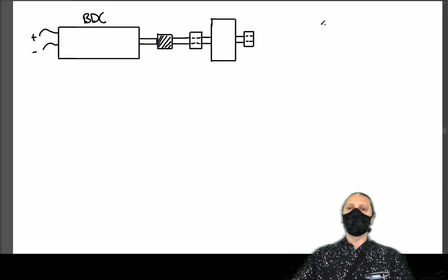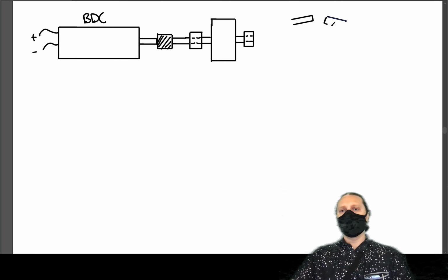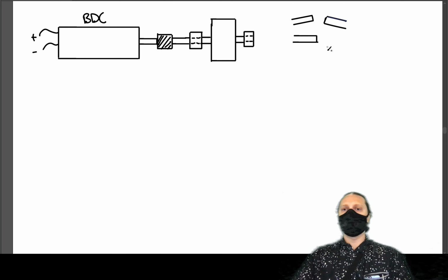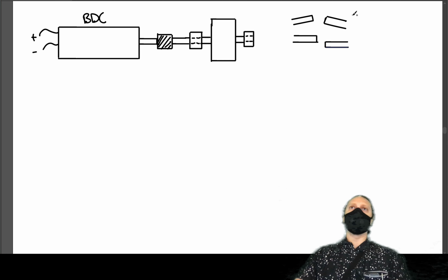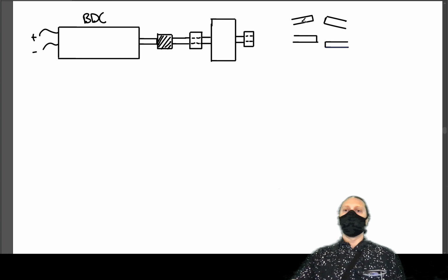There are two ways it can go wrong. You could have the shaft offset at an angle, so like one shaft is this way, the other shaft is this way. You could have the two shafts just translationally offset, so they're like this. These are both pretty extreme in the ways that they're drawn, just to highlight the two ways that they can be off: angle and just displacement.